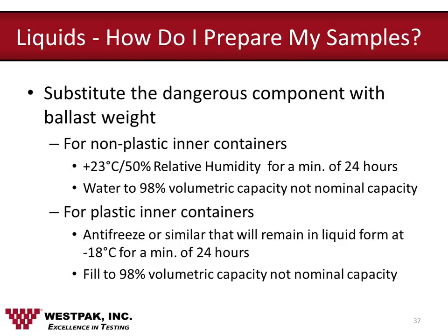Also, when testing with water, what happens is that the bottle expands, and hence you'll have false failures as well. And you must also fill it to 98% of volumetric capacity and not nominal capacity.